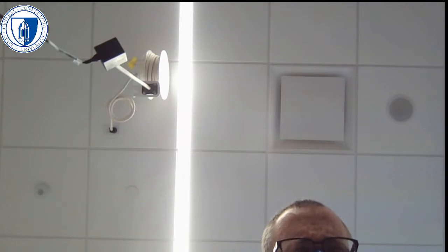So the yellow one is going to be, let's call that ZR2C, and that's going to be 2000, which is R plus ZC. I'm not going to type in ZC just yet. And then that ZR2C, the combination of the 2K and the 10 microfarads, is in parallel with ZL.